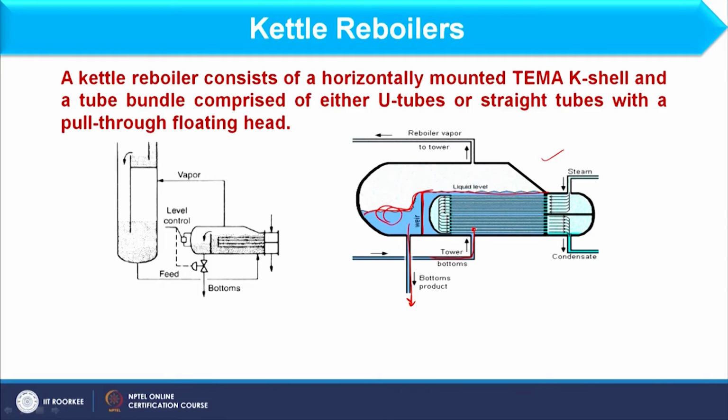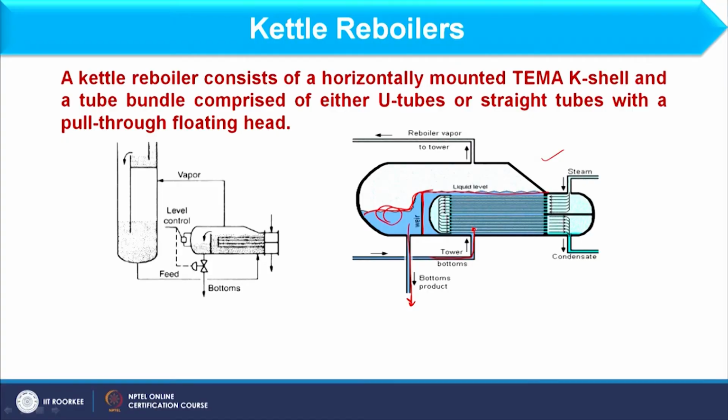Fine. Now, as far as shell and tube heat exchangers and condensers are concerned, we have discussed that baffle placement is different in both types. When I am focusing on the reboiler, we consider baffles in these types of exchangers also. Now, if you focus on this schematic, here liquid is coming from the bottom and starts rising upward through these tubes. In this case, movement of liquid is upward. Here I am not considering this type of flow or this type of flow, as we have discussed in heat exchangers as well as condensers.